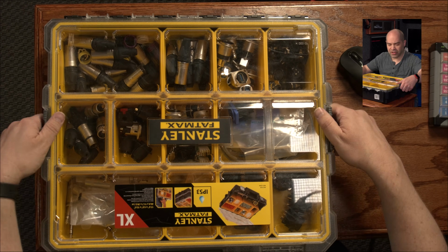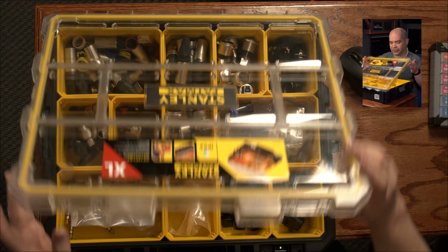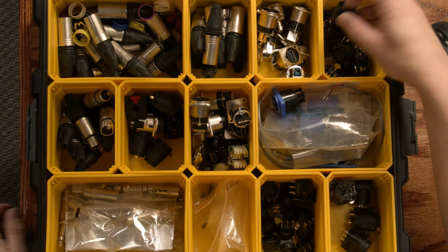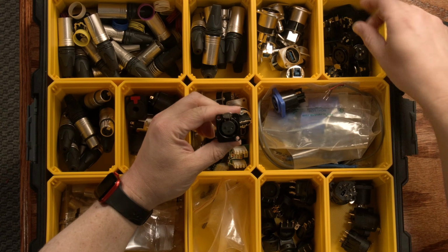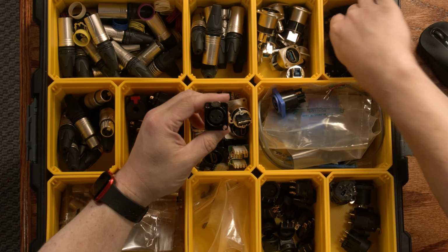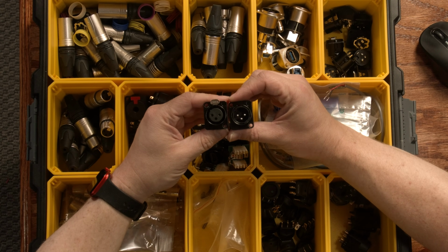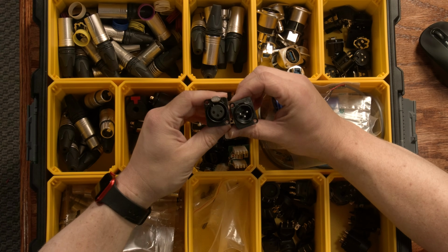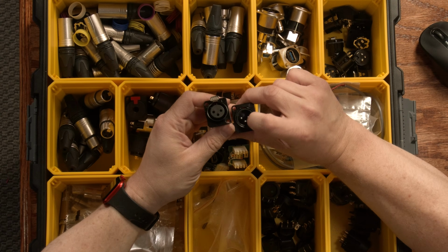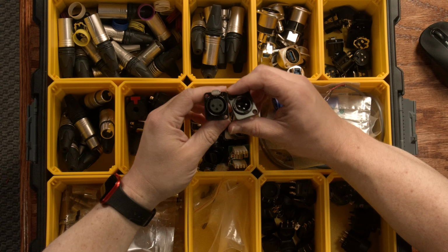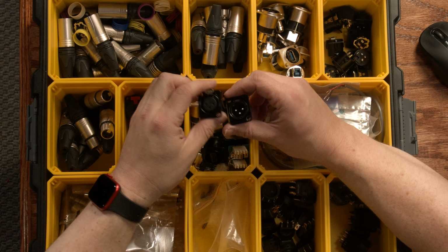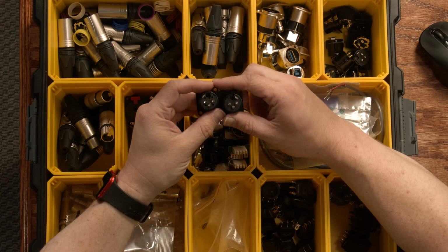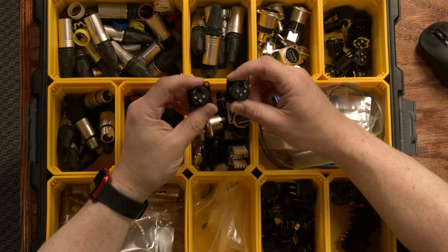Alright, so I keep a ton of these things around because they're just so incredibly useful. So move this out of the way and take a look at some of the options. So of course we've got our standard XLR. There's an XLR input and there's an XLR output. And these come in a lot of different variants as well. So you can get different metals in there. These are nickel, but you can also get them with gold. You've got some that use solder cups like these, and then there's others that use springs that are then meant to solder. And they also have feed-through connectors.